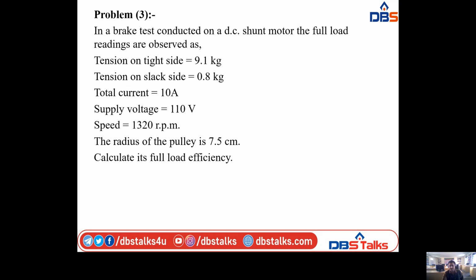On the left side we have the motor and on the right side we have generator, and the motor consists of the armature winding and field winding. So this armature and field winding consists of voltmeter, that is supply voltage 200 volts, and the motor field winding consists of the ammeter, that is 40 amperes. There is a motor input current 40 amperes and supply voltage across the armature, that is 200 volts.